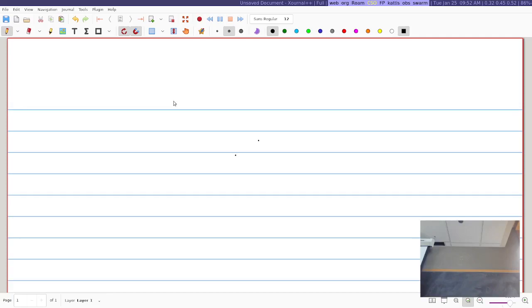Anything else? Yeah, Zach. The last thing I noticed was that troubleshooting in HDL was harder for me because it doesn't give you a stack trace or anything. It just tells you the program failed. Right, and you have to just figure out why. It is possible, if you have stuff loaded in the hardware simulator, to do things step by step and look at the values on the different internal pins. So you can do a little bit of debugging if you're wondering what is actually going on. But yes, it is harder for sure.